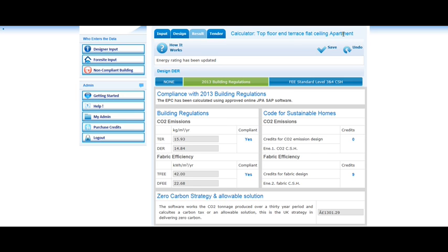We do not offer extreme fabric design with apartments because low air exchanges cannot be achieved because heat recovery systems are not suitable in apartment design. As we have said before, top floor apartments along with ground floor apartments are the most challenging dwellings to make compliant with Part L1A.